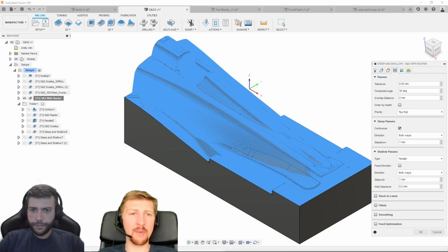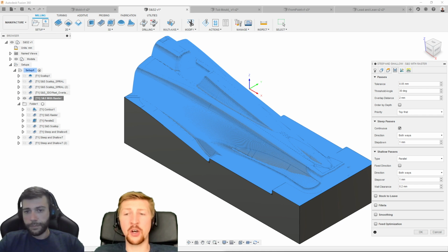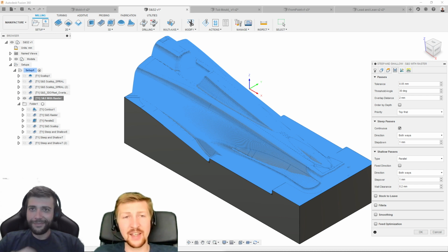Nice. I think one thing I do just want to say about this is that it's a toolpath that you could theoretically have done before steep and shallow, but imagine the time it would have taken you to create boundaries and define touch surfaces and then start trimming everything. And it doesn't matter if you're making a mold tool or if you're carving wood to make a sculpture. This is all stuff that is going to not only save you time, but it's going to reduce wear on the tools. You're not going to be rubbing the flutes on the side of steep walls. You're going to be creating a better quality component overall. So yes, you could have done this before, but it would have driven you crazy to have gone to it in this level of detail and produce this toolpath with just the few clicks that Fusion can do it with.